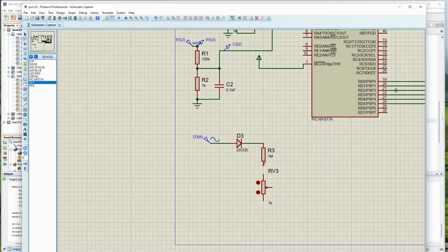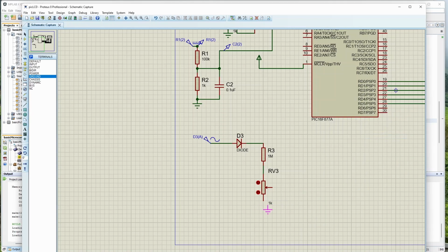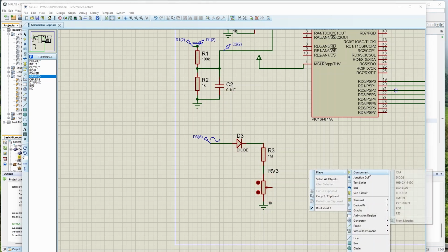But it is a good idea to use a transformer, step it down and also provide isolation, else this point on the board will be live. But in small applications you can directly use it. Terminal ground, connect this. So the bulk of the voltage will be dropped here, and this resistor I will use for tuning. So let me put a capacitor also. Now I have to use a bigger capacitor because I have to convert the sine wave into a constant DC.